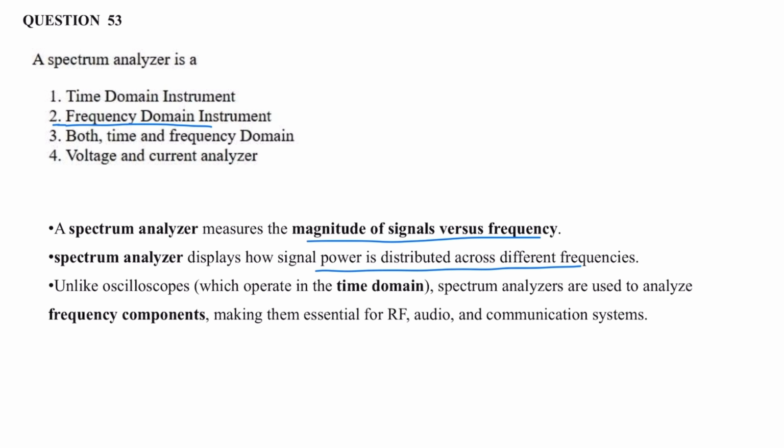Unlike oscilloscopes, which operate in time domain, spectrum analyzers are used to analyze the frequency components, making them essential for radio frequencies, audio frequencies, and communication systems. It is a frequency domain instrument. CRO is a time domain instrument.